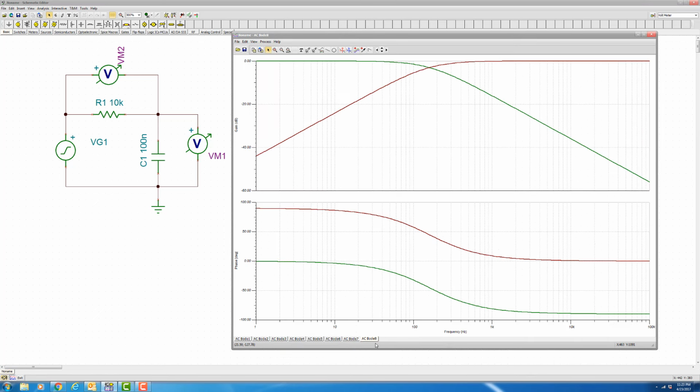Notice it added Bode 8. Now we've shifted. Now we're roughly here. Again, we're going to pull this over, type in -3. Well, I'll be, it's exactly a 10th. So I changed the capacitor 10 times in value, and it went from 1.59 to 159.